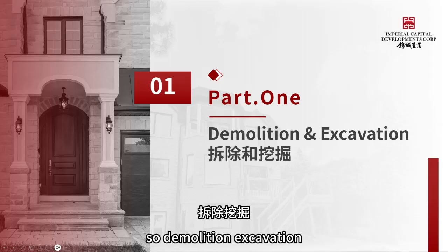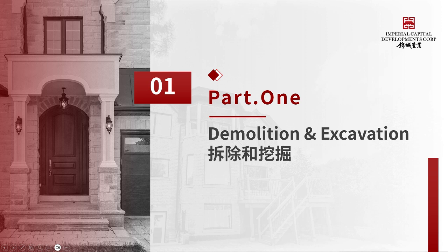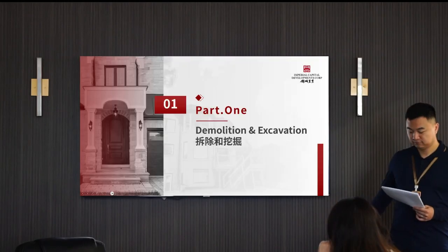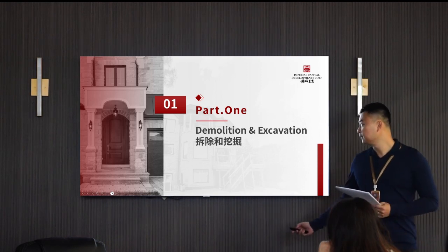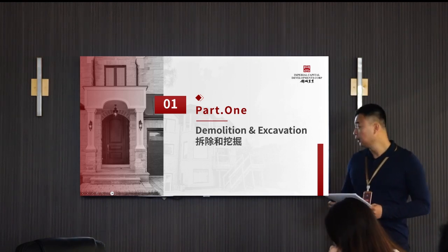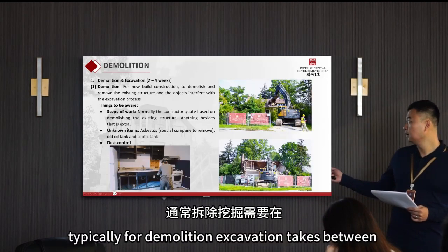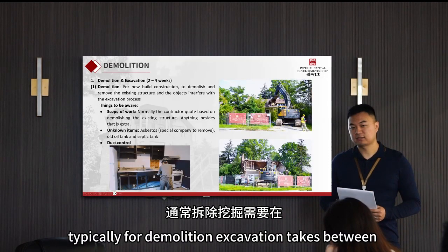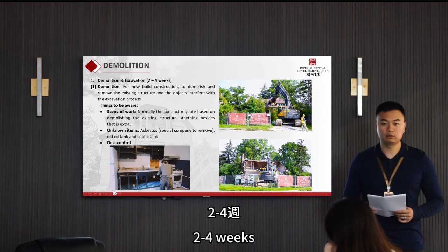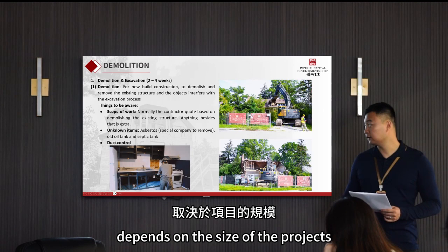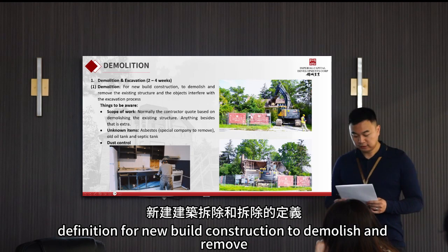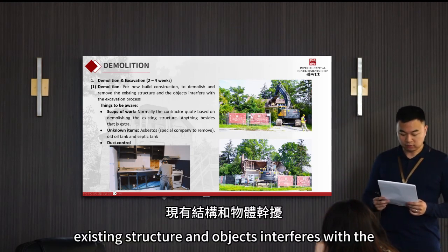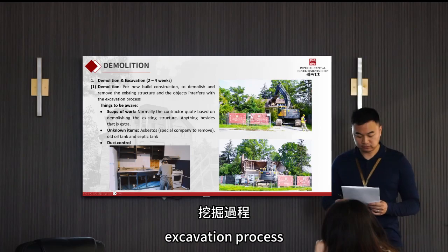So, demolition, excavation. Typically for demolition and excavation, it takes between 2 to 4 weeks, depending on the size of the project. Definition: for new build construction, to demolish and remove the existing structure and objects that interfere with the excavation process.